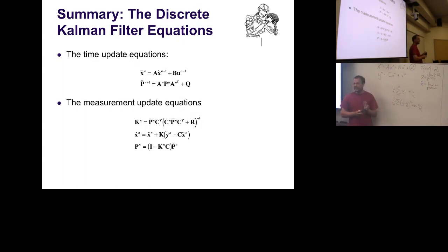Now, getting the noise on your process is harder, because you don't really know what to put there. This is where you start playing with the Q parameter. You scale it up a little bit, you scale it down a little bit, and you see until your filter finally performs well. Sometimes you get noise processes where the measured variance is really small. But if you make the measured variance really small, then the numerics of your Kalman update equation become a bit more unstable. So often people inflate it a little bit and are more pessimistic about it. Annoyingly, it turns out that of these two terms, this one you can physically constrain a little bit. This one is a guessing term, and you play with them until you get the performance you want.